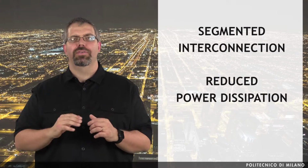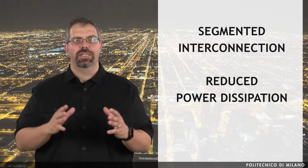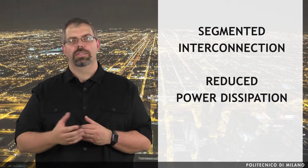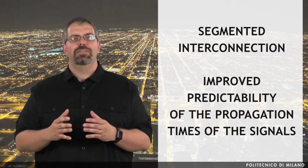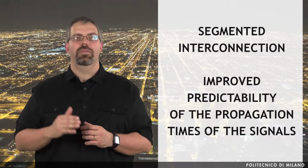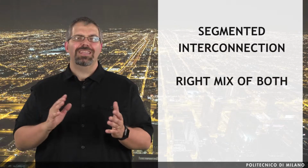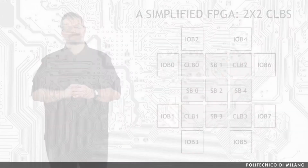On one hand, segmented interconnections offer a reduced power dissipation because the resistance and capacitance of the interconnection lines are only those of the interconnection length between the blocks. On the other hand, the main advantage of direct interconnection is that parasitic resistance and capacitance are almost constant, resulting in an improved predictability of the propagation times of the signals. Therefore, having the right mix of both is going to guarantee us the best performance.